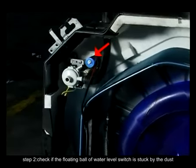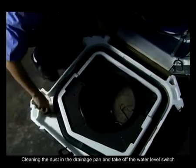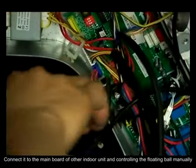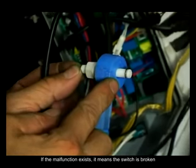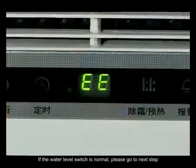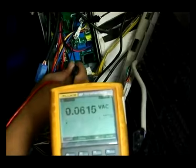Check if the floating ball of the water level switch is stuck by dust. Clean the dust in the drainage pan and take off the water level switch. Connect it to the main board of another indoor unit and control the floating ball manually. If the malfunction exists, it means the switch is broken. If the malfunction disappears, it means the switch is normal. If the water level switch is normal, please go to the next step.